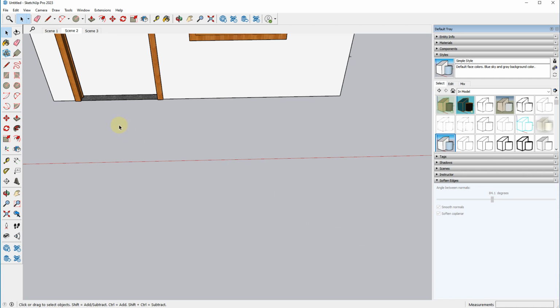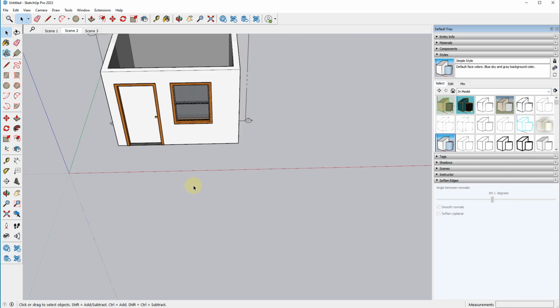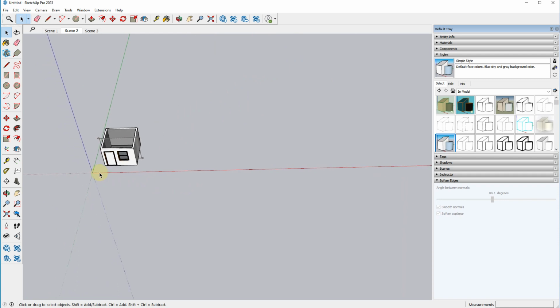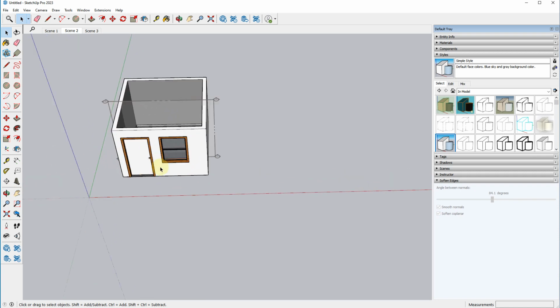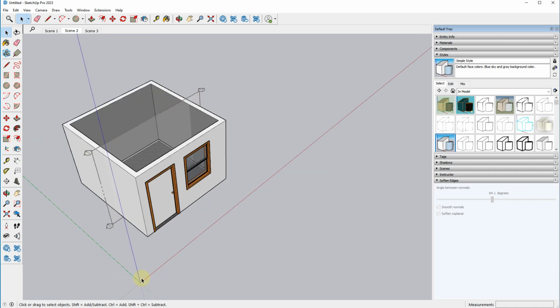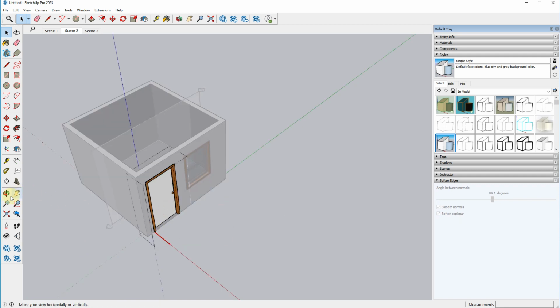One of the other tools that I didn't mention, but I kind of accidentally started using, was this one right here, the axes. If you are generating a component, you want to set, how do I put this? It redefines where the 0, 0 is for things. So if I go into this model right here, you can see that this little red, green, blue axis thing is right here. But if I get out, it's over here. You can redefine where these axes are defined with this.